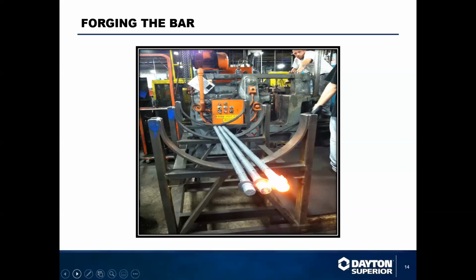That way, when we cut the threads into the bar, we no longer infringe on the cross-sectional area of bar that is required to achieve the strength of the rebar.